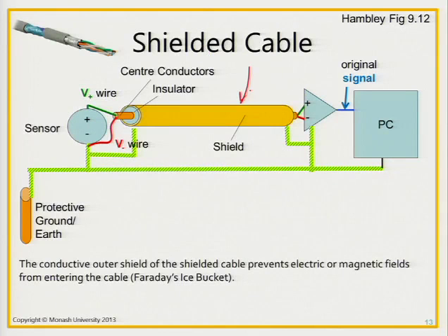They're called coaxial cables. In the middle there are conductors, and around it there is a metal shield. It might just be like thin aluminium foil. What that does is stop electric fields from getting in there, electric coupling. And so that's another way we can reduce noise getting into our signal wires.